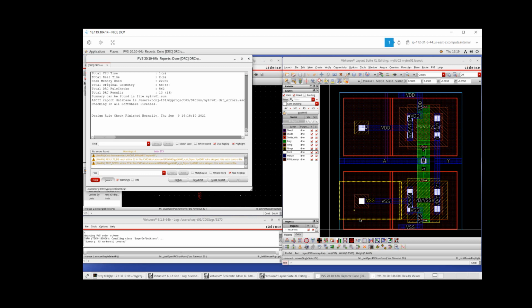You don't have to have one body connection per transistor, and the reason is that it's very expensive, as you can see, because in the case of this PMOS, we have to use an implant to tie the n-well, and the implant regions of different polarities have to be quite far apart by design to be able to fabricate it. So that adds all this space here that is very expensive.